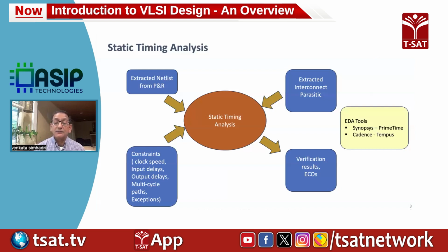And so it gives you an output file that you can go through and analyze the results and identify the problems and generate ECOs to go back and change the design, fix these problems to make sure that the design meets the timing. Again, it's an iterative process. People talk about physical design that takes RTL netlist and gives a clean GDS2 in one go.